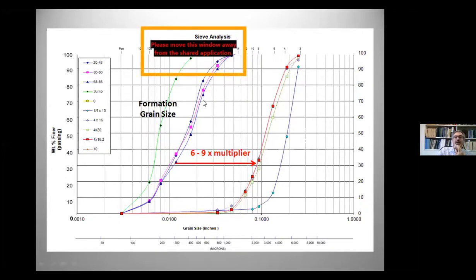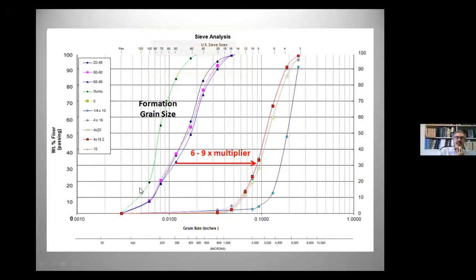So we're looking at the gradations of, say, a sampling of some of the formation samples here. So this would be the finest portions of those samples, the mid-size, and then the coarser sections are here, mid-size, and the fine fraction would be down here. So silts and clays would plot down usually low and to the left.